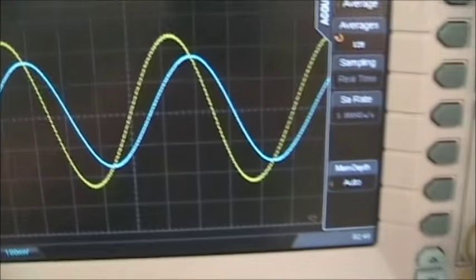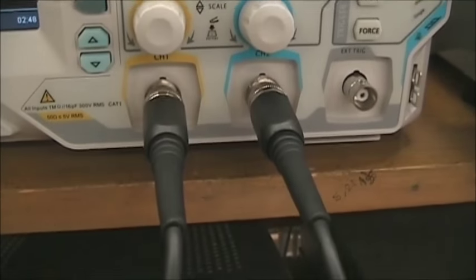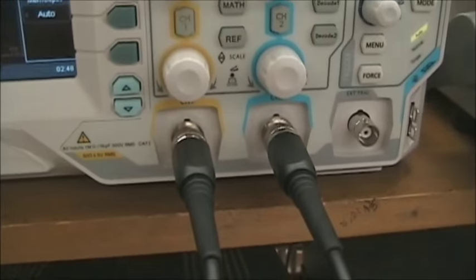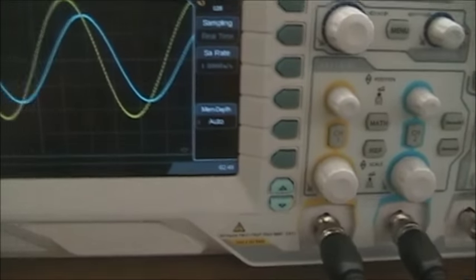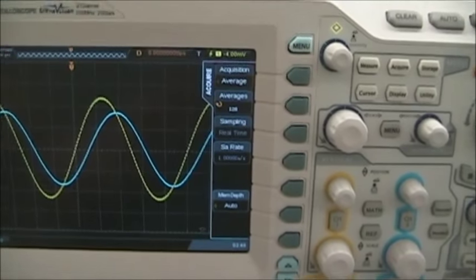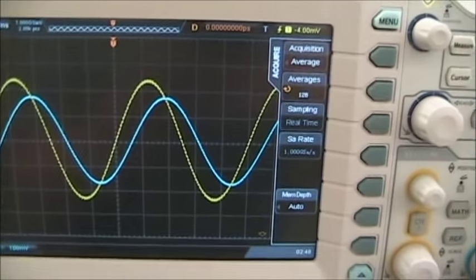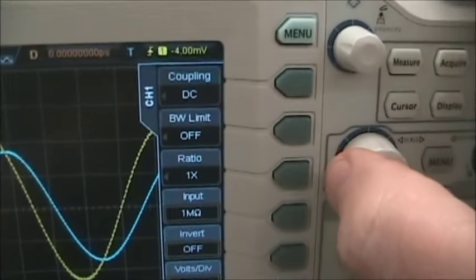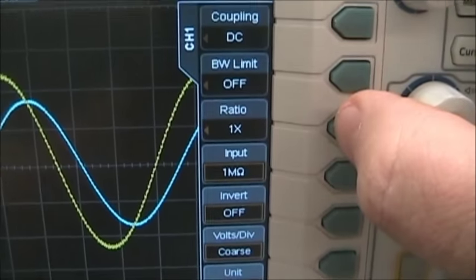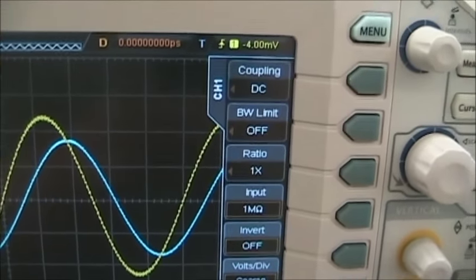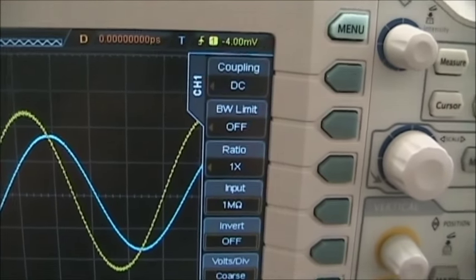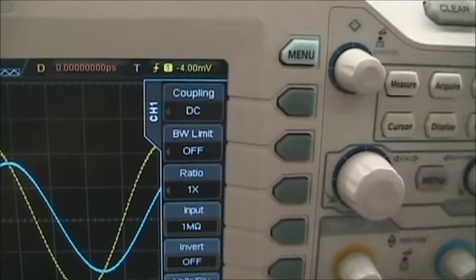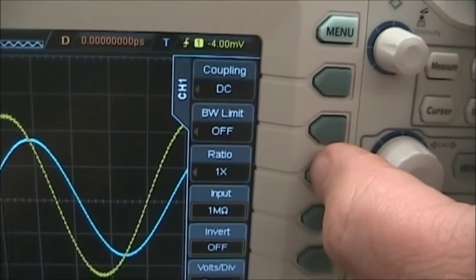But also, in this case, we're using ×10 probes on our scope. Generally, if you're going to work over a couple hundred kilohertz, you should use a scope probe. So if I press 1, I can set the scope ratio. Now, if that was set by the last user, it may or may not be in your configuration, so you should always check that.